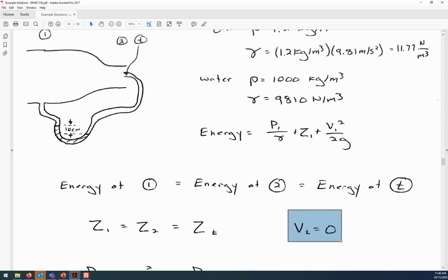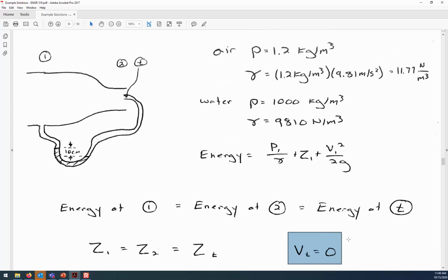I have a question real quick. Mm-hmm. I've been looking at the air properties. So it has 1.2 kilograms per meter cubed times 9.81 meters per second squared. Yep. You get 11.77 newtons per cubic meter. In water, we do it a little bit different. So, well, water we know offhand, but wouldn't it be 98.10 newtons per meter cubed? Okay, I see that wouldn't be right.